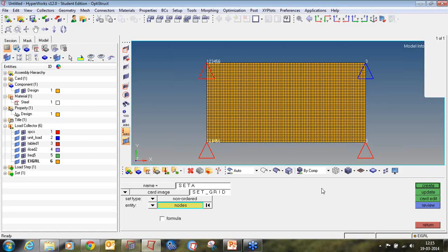With an FRF simulation, the amount of data generated can easily create a big result file. It is a good practice to work with a set where the user can specify only the points of interest. This will reduce CPU time and the amount of data to be saved.